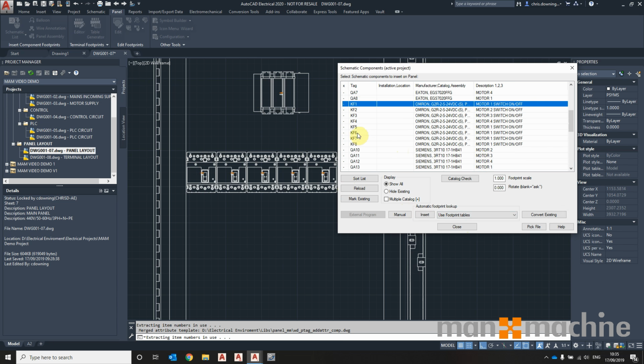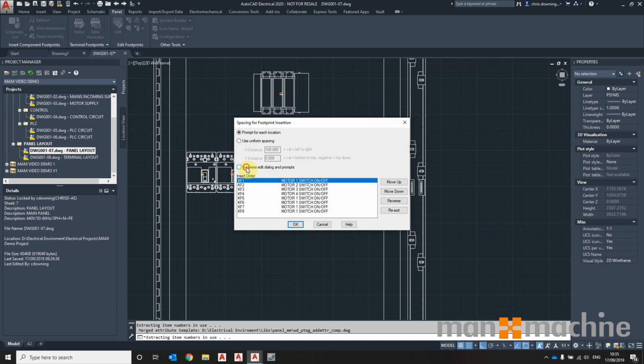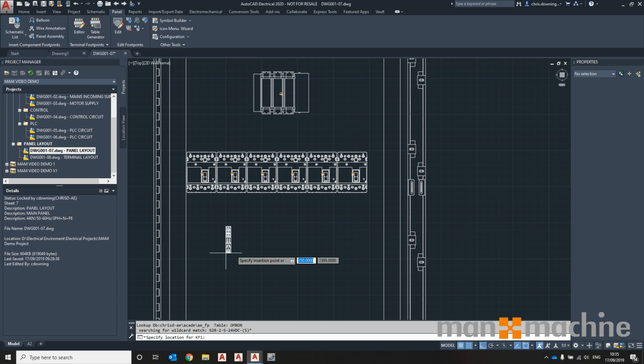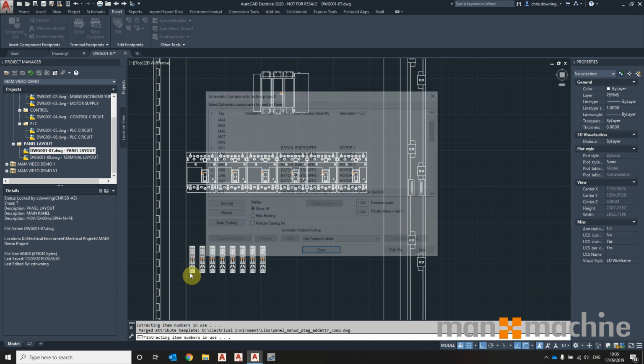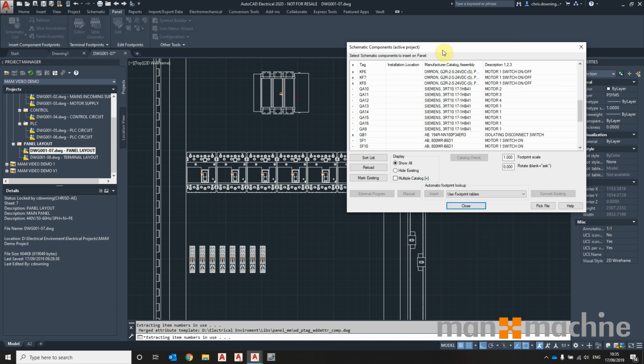So now I'm going to put in my relays, insert those, suppress dialog box, spacing of 35 probably, something like that. A bit much, but yeah, you could get that exactly right if you knew the width of your circuit breakers. Sorry, your relays.